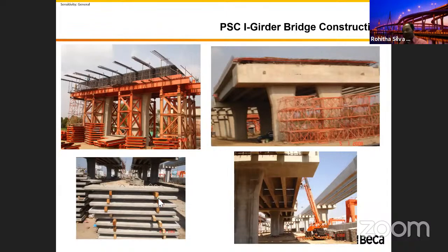We replaced the formwork with the plank, and then we designed the whole bridge as a composite section, right? Because this bridge we designed as a composite of the I-girder and the slab. Then in addition to that, now we got another pre-stressed concrete plank. We got a pre-stressed concrete plank, and then we got the I-girder, we got a bridge deck. There are three elements. We combine them together, we redesign.